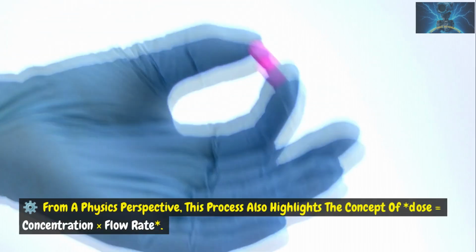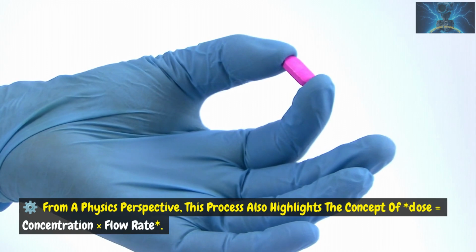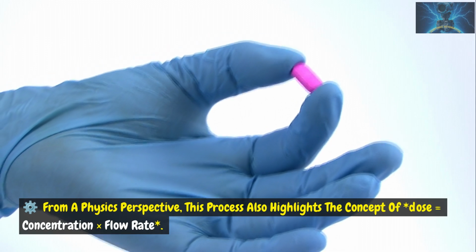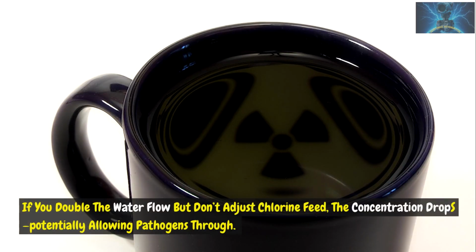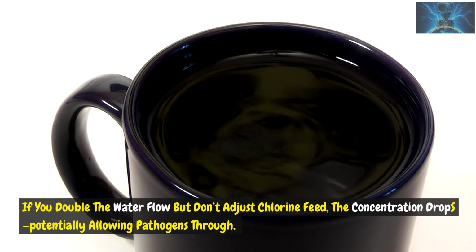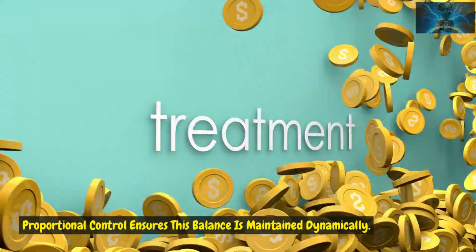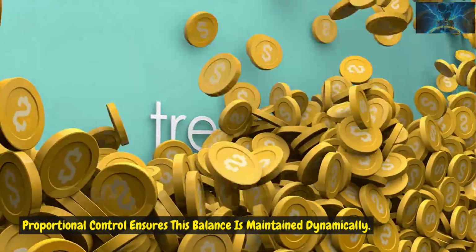From a physics perspective, this process also highlights the concept of dose equals concentration x flow rate. If you double the water flow but don't adjust chlorine feed, the concentration drops, potentially allowing pathogens through. Proportional control ensures this balance is maintained dynamically.